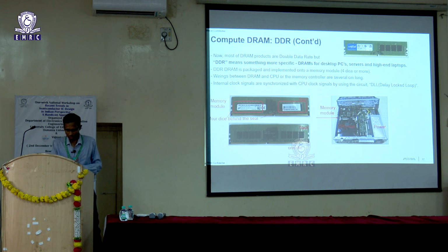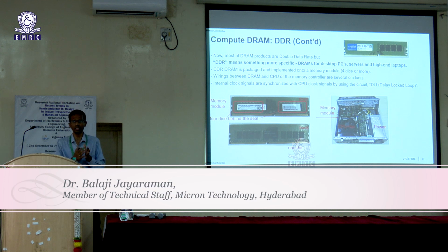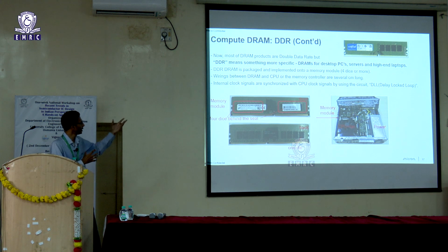A bit more on compute DRAM. As I said, we use this in the context of DIMM modules. If you have seen these DIMM modules in a laptop, this typically spans a few centimeters. Now this has to interface with your CPU. The CPU will drive clock as well as data, and you have DRAM chips lined up sequentially. So you need a mechanism wherein you can synchronize the clock that's driven out of the CPU and reaching your DRAM with the data that's reaching it there. That synchronization is done using an internal DLL. Every DRAM will have its DLL, so that whatever comes in, the clock as well as data, are well synchronized.